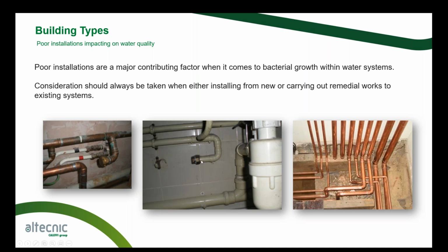The bacterial growth can sit there if there's ambient or transitional heat that goes through there. That water can start to warm up, you get the bacterial growth. There's no turnover, there's stagnant water. It's going to be an absolute breeding ground there for the bacterial growth.